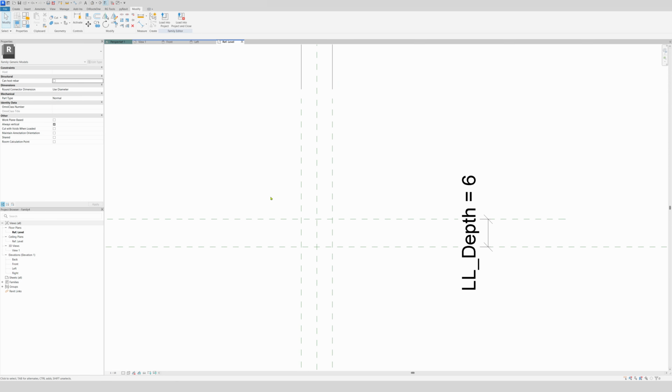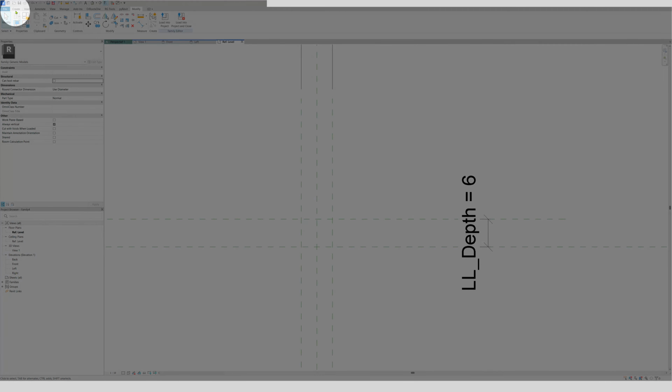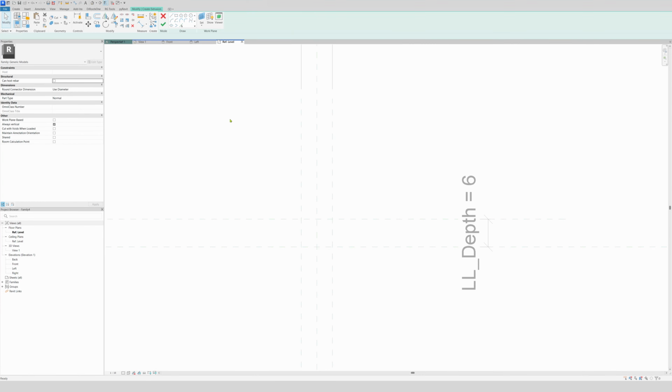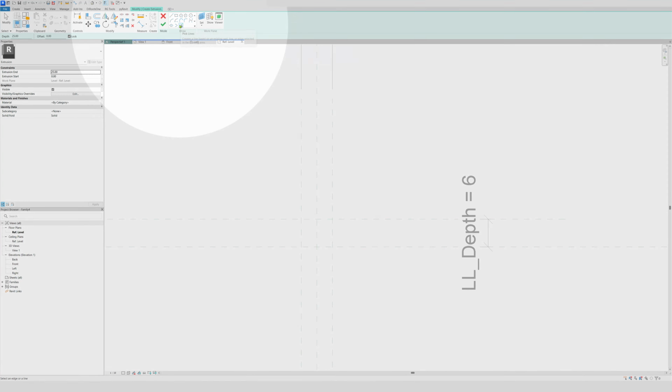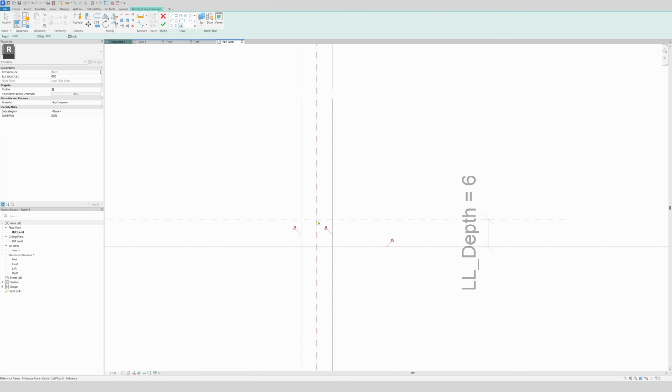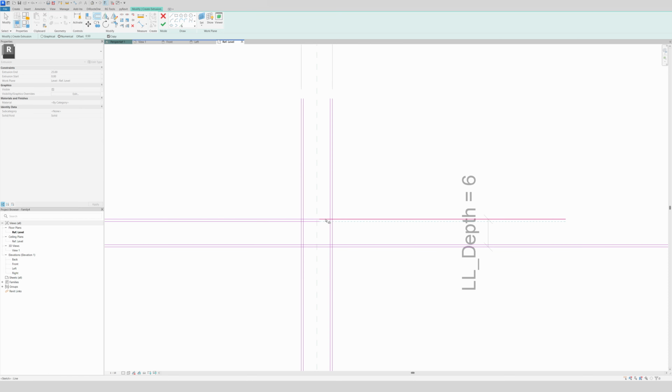And now we're gonna make the extrusion. So we're gonna do create tab, then extrusion, and then pick lines and make sure it's locked. Then constrain it. Voila. And I will split it, so SL, and then give it an offset OF of just 50. And then right here we do it like this.